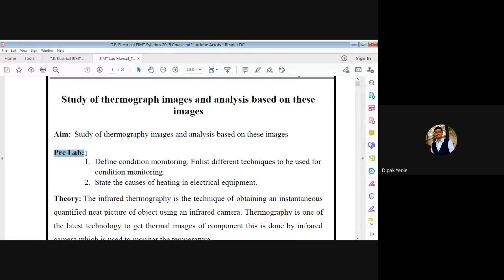Yes, so if you are interested in doing a regular checkup of your electrical fan, that can also be called condition monitoring. But no doubt we have to use standard procedures. So either we use vibration analysis, oil analysis, ultrasound analysis, or thermography analysis. Based on these standard procedures, it is called condition monitoring.